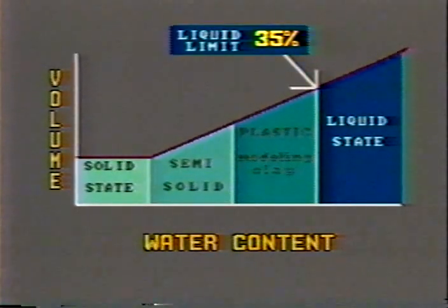Fines are a mixture of clay and silt that should have enough plasticity to bind the sand and gravel together. The liquid limit of fines should not exceed 35, or the road will become very soft during long periods of wet weather. Liquid limit is the water content where the material becomes more liquid than solid. The ratio of fines to sand and fines combined should not exceed 2/3.